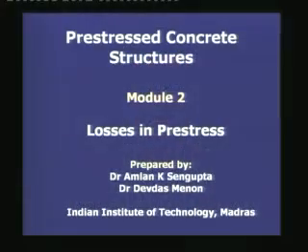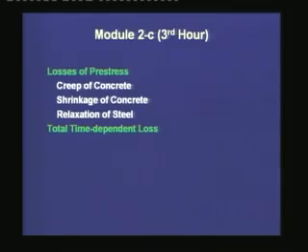Welcome back to Prestressed Concrete Structures. This is the third lecture in the module on losses in prestress. In this lecture, we shall study the long-term losses of prestress due to creep of concrete, shrinkage of concrete, and relaxation of prestressing steel. We shall also learn how to calculate the total time-dependent loss.